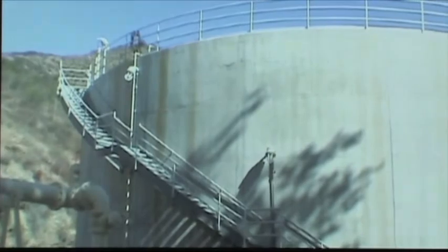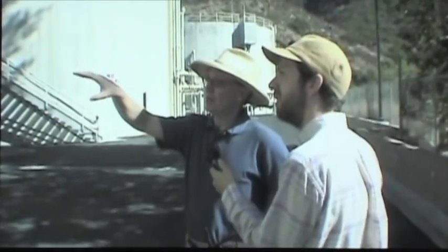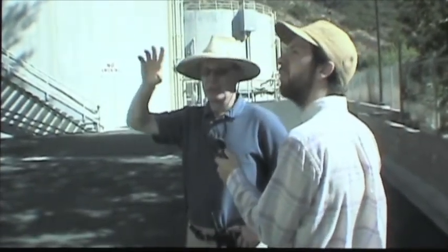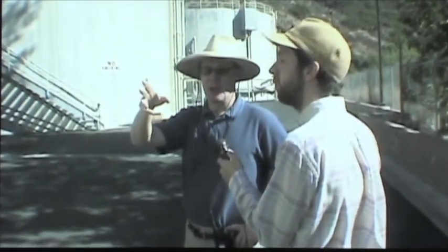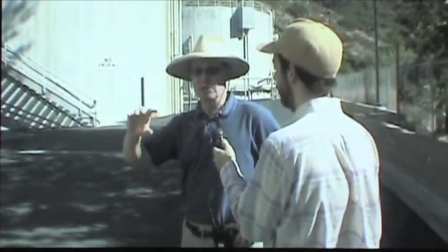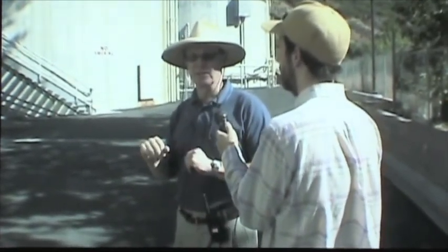So are we hearing the flaring going on right now? Is that what that is? No, you don't hear the flare. Those are just the pumps. There's actually valves opening up as things are being pumped. They're just pneumatic valves, and it's getting pumped from 2 sources. One, the primary sludge comes in its own particular fashion, but also the processed material that comes in off the aeration tanks. Right. We solidify that quite a bit, and so we get 5 to 6% solids.